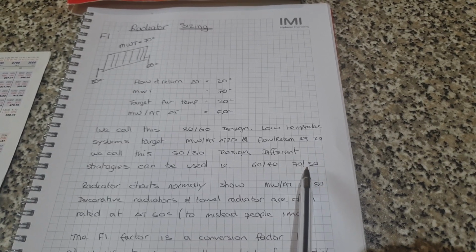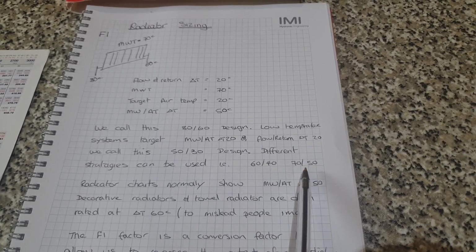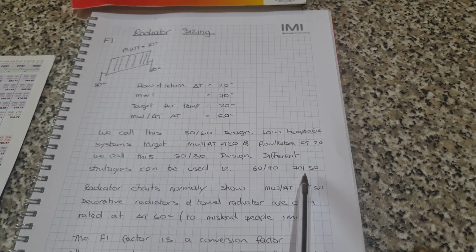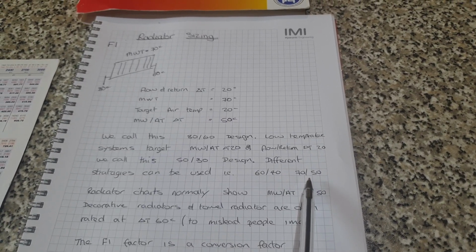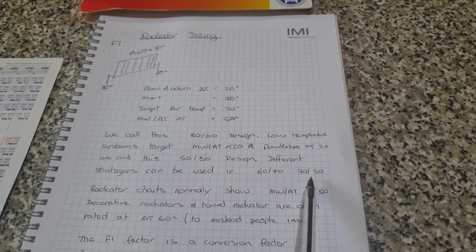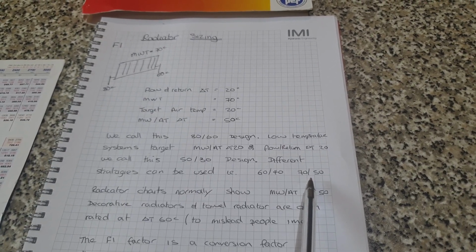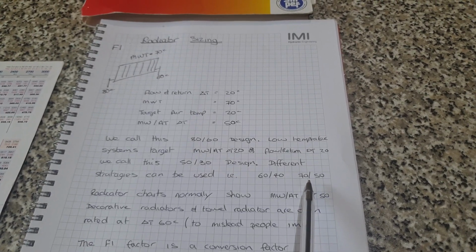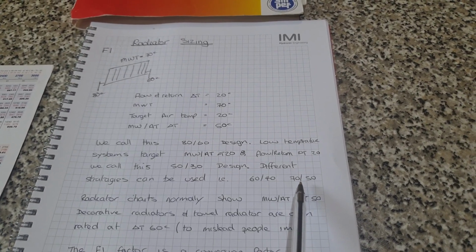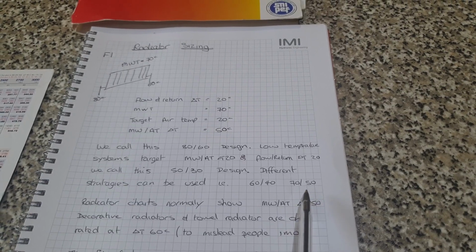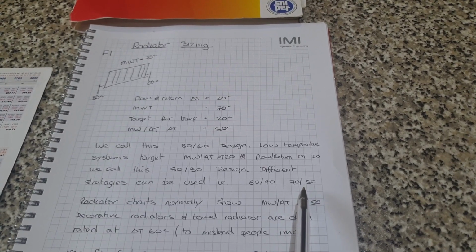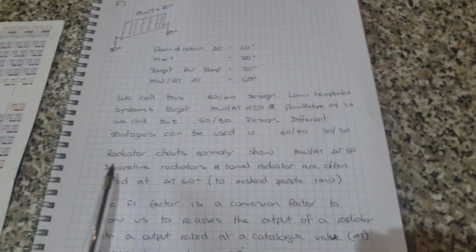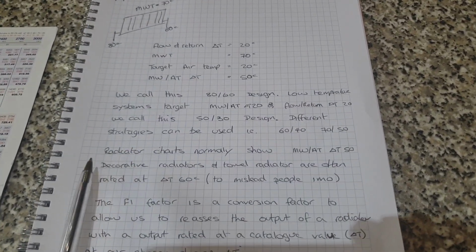If you were using weather compensation systems, you could mix and match a little bit more if you were using something like Evo Home. Something like Evo Home will compensate for poor design and for poor radiator selection, and you could argue that you could actually do a better design using Evo Home if you wanted to make that argument. I don't think I'd agree with it, but it's one of those arguments that would fall down more to opinion, I think.